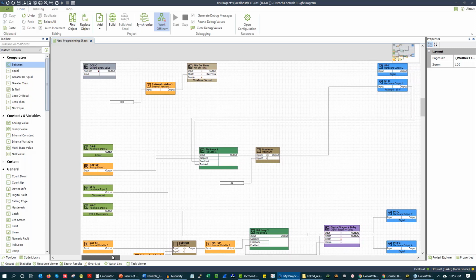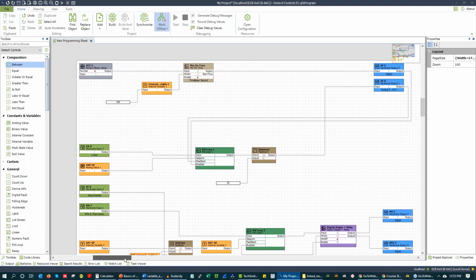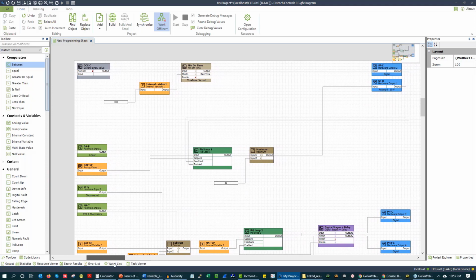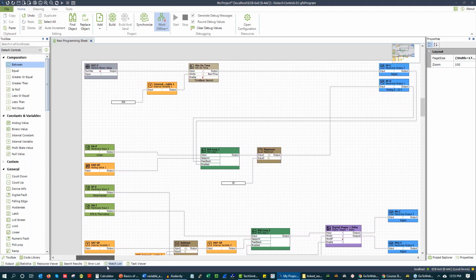Anything. I mean, EasyIO CPT, Distech GFX. I think both of those are free software if I remember correctly. And so I would recommend that. They both have simulation, although EasyIO CPT is live programming and GFX is compiled.